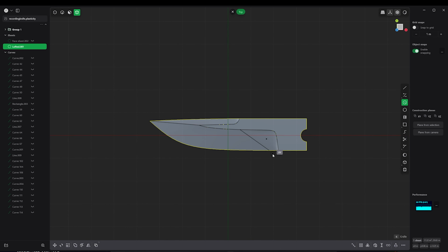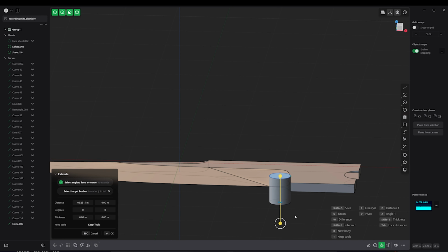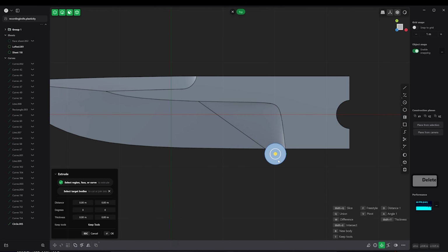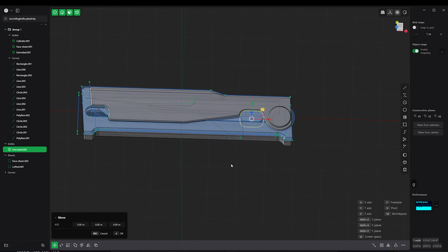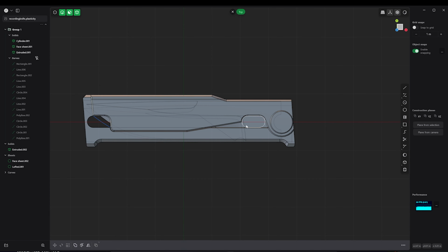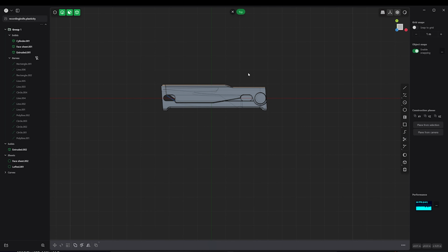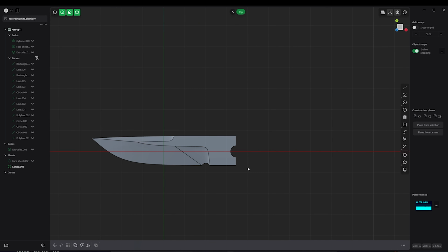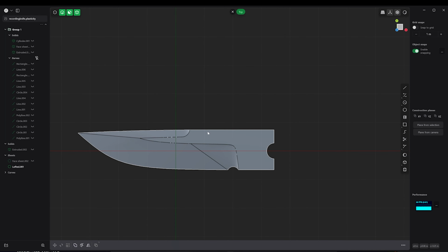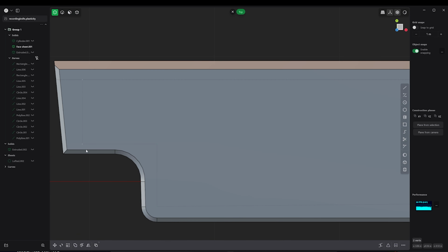But yeah, I basically went in and did it again using this surfacing setup, taking examples from other surfacing attempts that I've done and other artists that I've seen on YouTube doing mostly surfacing-based workflow. And it seemed like when you're doing surfacing, it's best to lay out the curves and then loft your surfaces and then connect them. And this piece here, I actually had trouble getting it to turn into a full solid. That was another thing that I've learned over the course of this beginning modeling: you've got to make sure that pieces are solid.